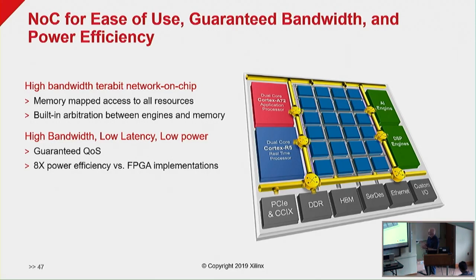So this is the network on chip. These are mid-range parts. This is a 1 gig network. It's 128 bits wide. There's a kind of vertical component to it and a horizontal component, so VNOC, HNOC. The VNOC is, let me just get this right, the VNOC is maximum of 2 channels, the horizontal NOC is maximum 4. That gives you 64 gigabytes per second bandwidth in the horizontal NOC, just that. And the processors actually access the DRAM through the NOC.